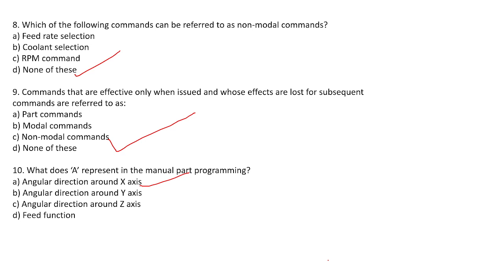I know about block. A block is a line of code which contains all the instructions. For example, the first block would be the first list of instructions like coolant on or tool selection, and workpiece is the actual workpiece to be machined. And character, I think, is the actual command. Character is that digit or letter or symbol which you can see, like N1, M, or a type of command which we are going to input in the CNC machine.